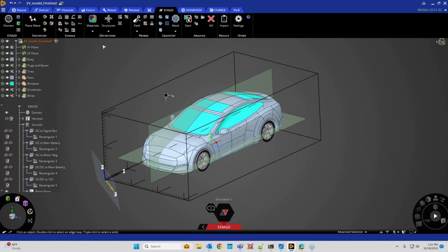And then you need to assign the materials. So you just click materials, you select something, either an isotropic surface, anisotropic, frequency dependent. We have a bunch of different options here. And my computer is going to auto save right in the middle of this. I apologize.